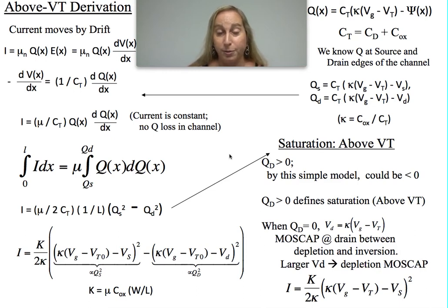than the threshold current, which means that the charge itself will terminate some of the field lines as I go from source to drain. Now I've got a change in the potential. One of the things that comes out from having this significant change of potential is that the current's moving by drift. Basically, I expect that there's a change in my potential from the source edge of the channel to the drain edge of the channel by more than UT. If it was less than that, then we'd probably go, yeah, it's relatively flat and it's mostly all moving by diffusion and it's basically a subthreshold model.